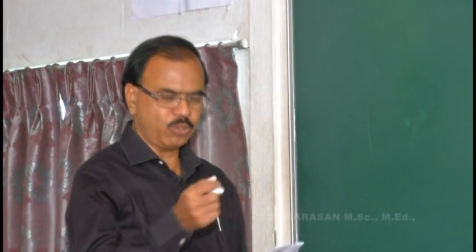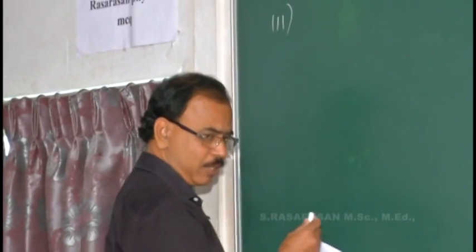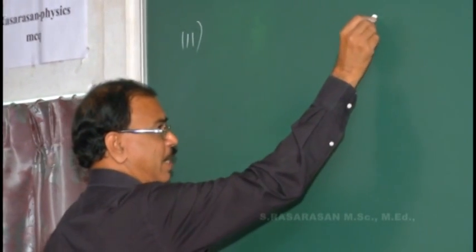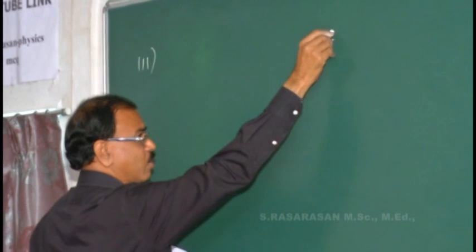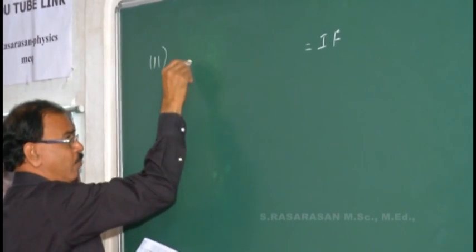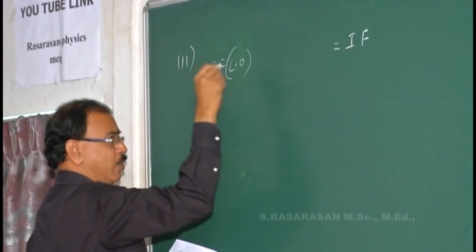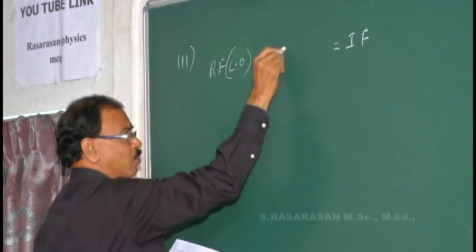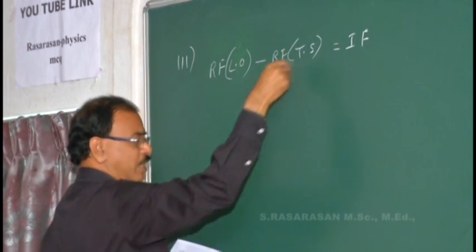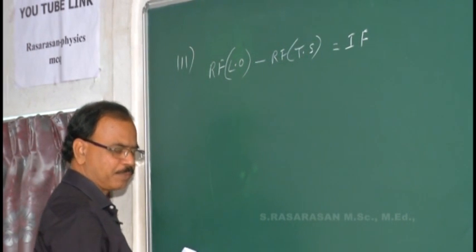So to tune a radio station of frequency 900 kilohertz, our radio having a local oscillator, that oscillator should produce a frequency of radio wave. What must be the frequency? What is called intermediate frequency? Intermediate frequency is nothing but the radio frequency wave produced by our local oscillator in our radio minus the radio frequency of the tuned radio station or broadcasting station.